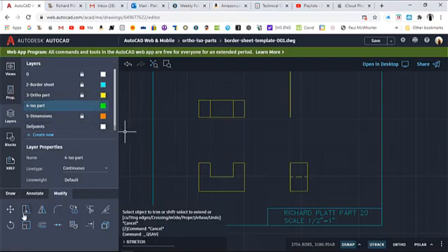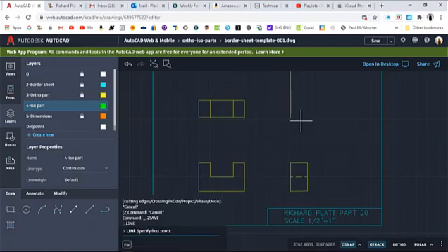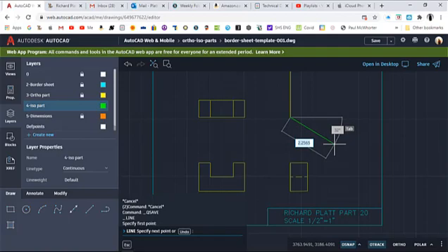Okay, again, we put that one line in right here, so that would be our starting point. That's based off of a 2 inches gap between each of the top, front, right, and ISO views. So we'll go ahead and start with this, and we're going to come over here and just let it snap to this point here. We're going to come out 2 inches, excuse me, 2, not 20, hit the tab key and go 30 degrees.